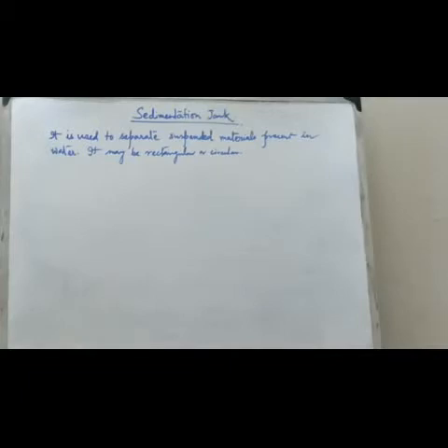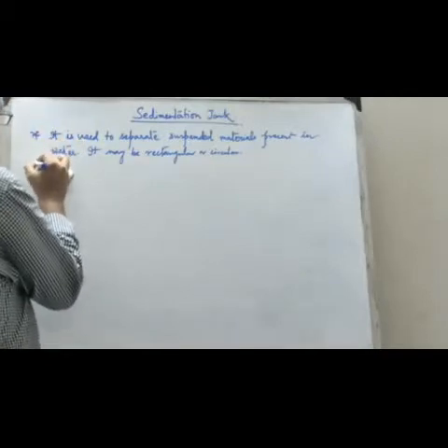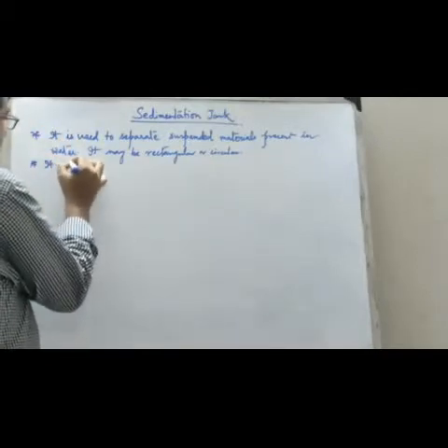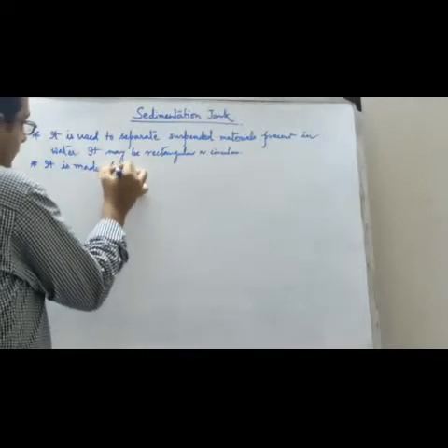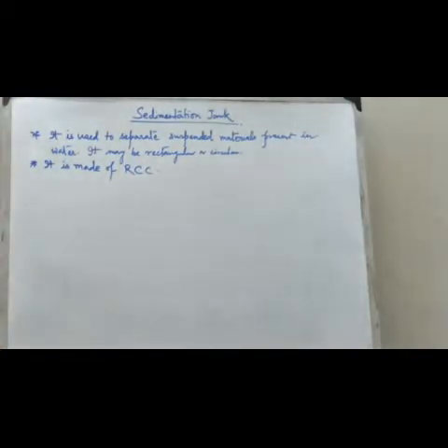So these are the sedimentation tanks. By this sedimentation tank we actually remove the suspended material. These sedimentation tanks are generally made of reinforced concrete, and may be circular or rectangular in plan. So please write down the second important thing: it is made of RCC, that means reinforced cement concrete, which I have already discussed in my design classes.